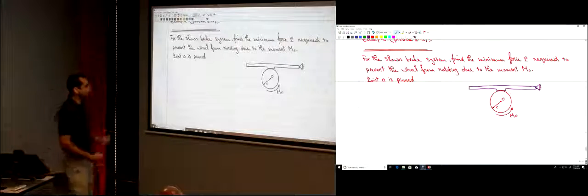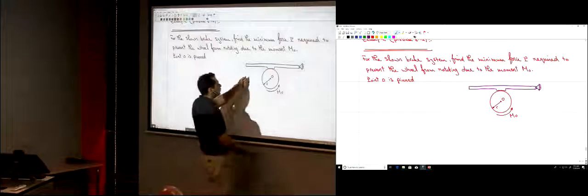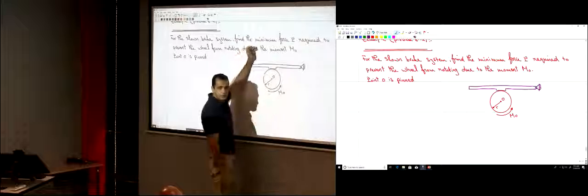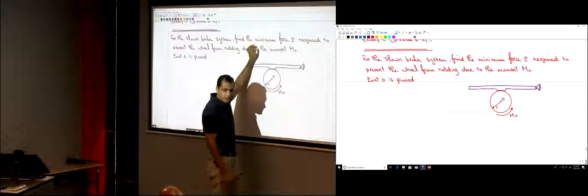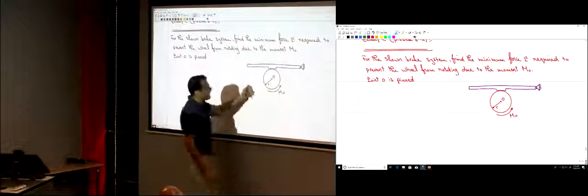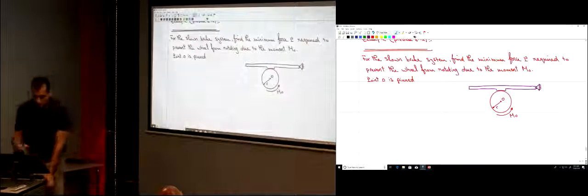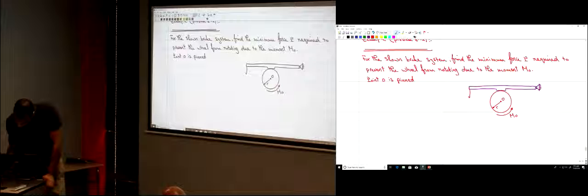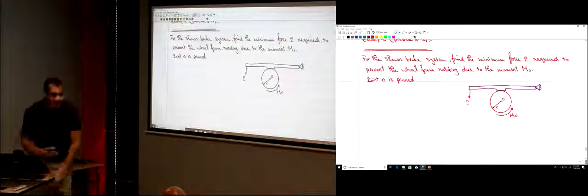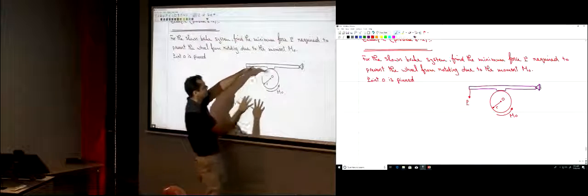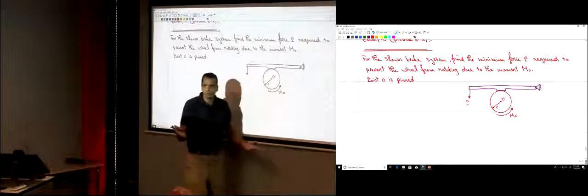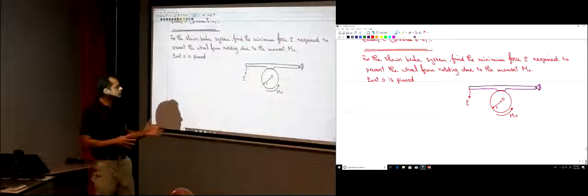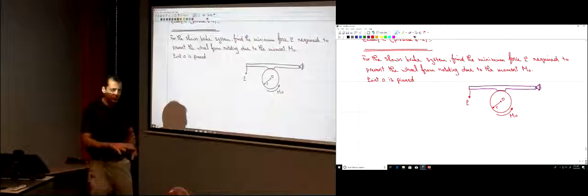So if you want this wheel to rotate, you just move this up, it's going to rotate smoothly, nothing is preventing it. If you pull this down here, it will interact with this wheel to prevent it from rotating. So if the wheel is rotating, it can stop it from rotating.